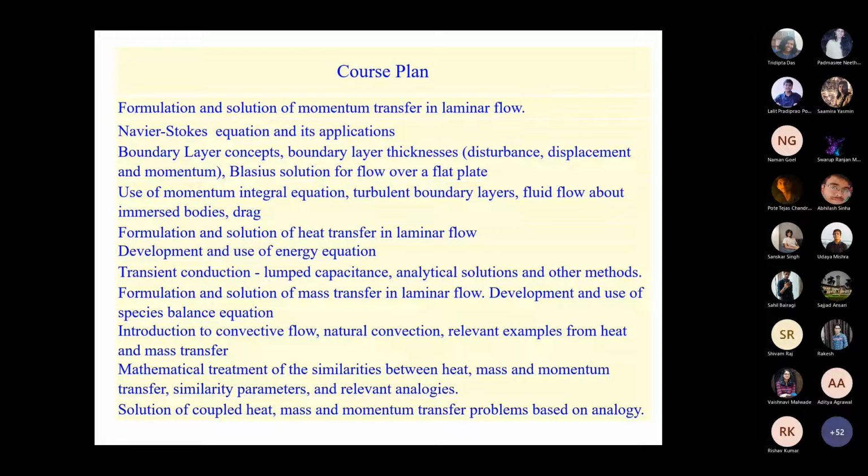Since we are talking about the change in temperature inside the solid object, for the Biot number the k is going to be that of the solid. So the differentiating factor between the Nusselt number and the Biot number is that the k in the Nusselt number is that of the fluid, whereas the k in the Biot number is that of the solid. And we know that there are certain values of the Biot number, I think less than 0.1, for which the lumped capacitance model is valid.